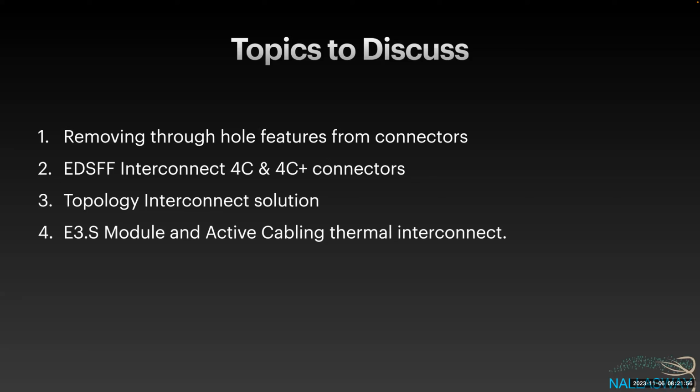The topics I want to discuss are the challenges we have to address with this modular approach. First, we need to remove through-hole features from all the connectors we use. That's a critical thing, and I'll show you why. Then we leverage the EDSFF interconnect, specifically the 4C and 4C plus connectors, and take a closer look at what we're doing with them and the tweaks we might need.